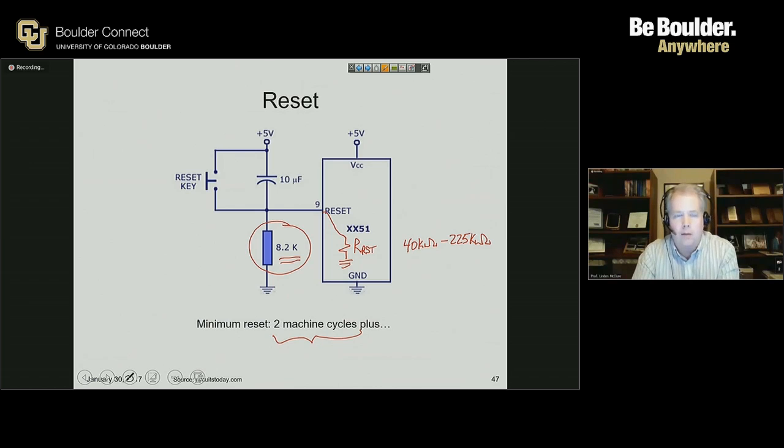So if I had to have a situation which was more tightly controlled, I could achieve that in a pretty low-cost way just by adding on an external resistor which dominates that resistance parallel combination. Does that make sense? If it makes sense, raise your hand. Great, thank you.